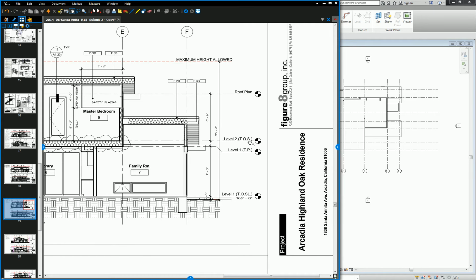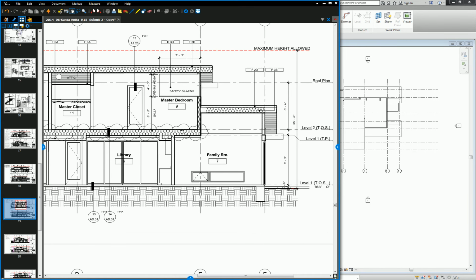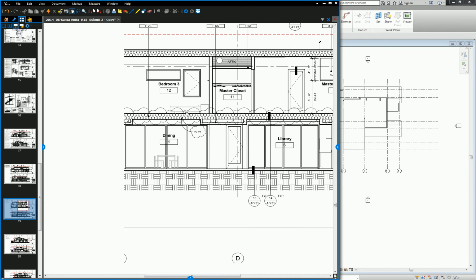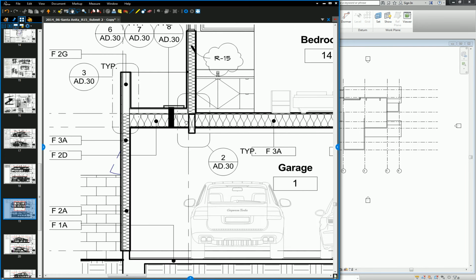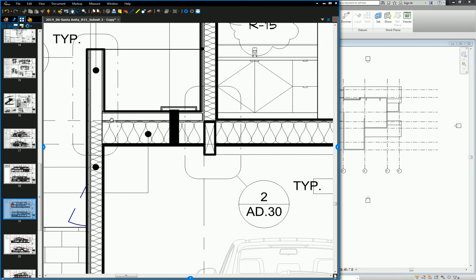Along level 2, you see the interior floor here, right? And that carries across through the interior spaces, and then it transitions directly to exterior. So theoretically, from a BIM perspective, we can model this the same way, assuming it's framed out of the same elements. So especially at this stage, since we're just doing a schematic model, what I'm going to do is model that second floor, interior and exterior, as one contiguous diaphragm.